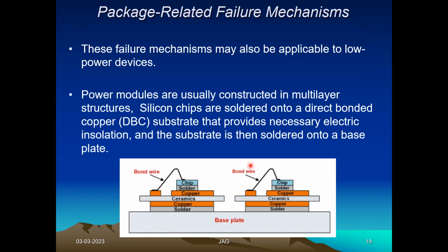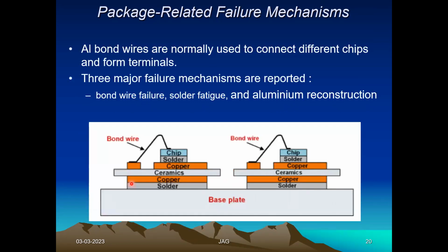So when the number of cycles is large, say 50 times, this is happening in 1 hour. Temperature increases from 20 degrees to 50 degrees. After some time, it went back to 10 degrees. Again it went from 20 to 50 degrees. If such a cycle is repeated, what will happen? Definitely, this bond wire also experiences a cycle of stress and strain. These joints are also experiencing continuous cycles of stress and strain. This will weaken and ultimately break down. Am I right? So this is the problem that can happen due to the difference in coefficient of thermal expansion, CTE.